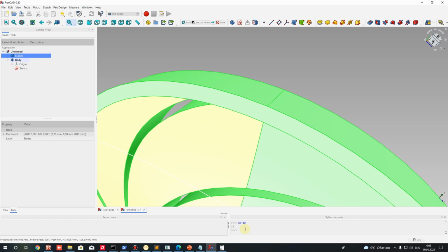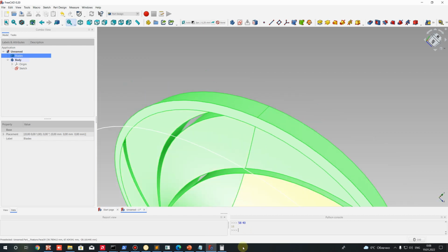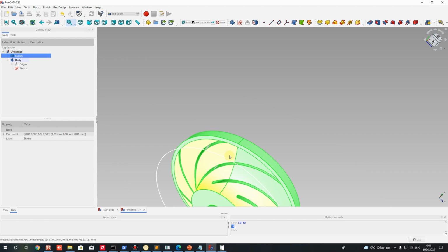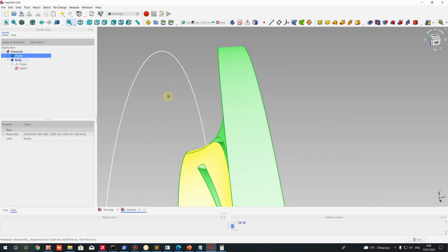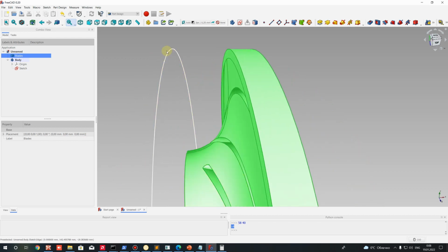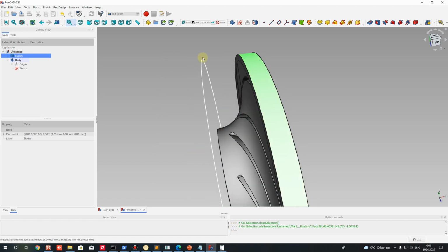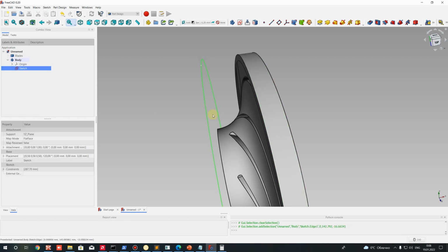So after that, let's create the width for our CFD domain. We have to use this value for the connection of this part and this external face, if we extrude this surface in X direction.